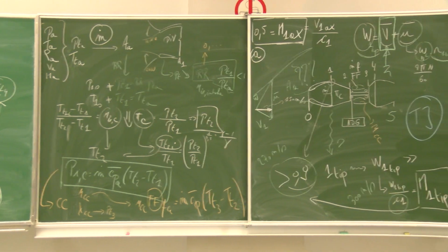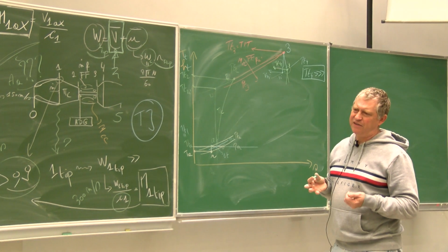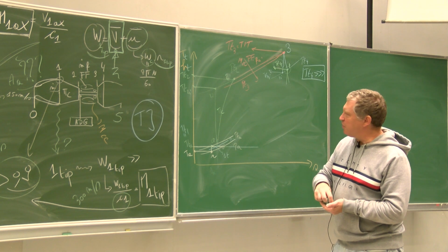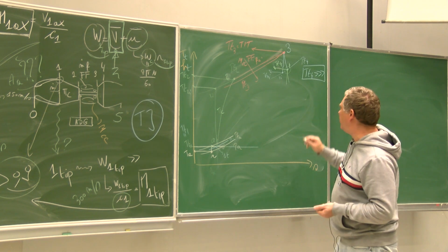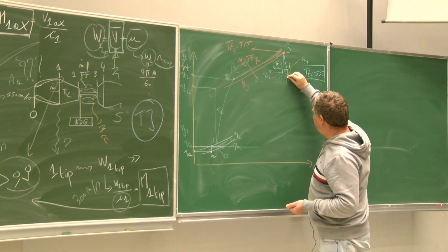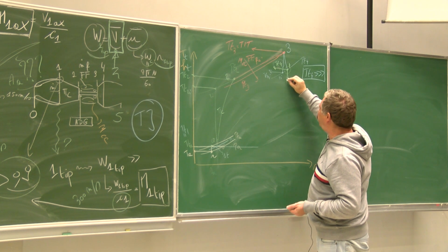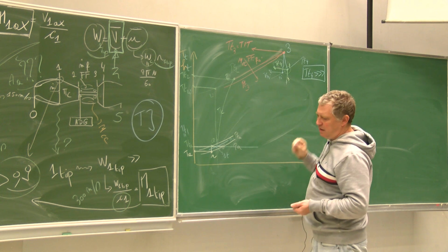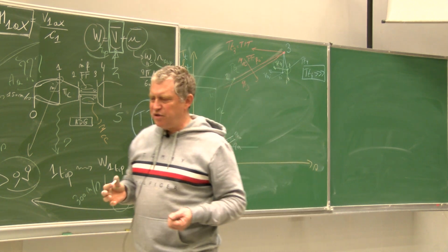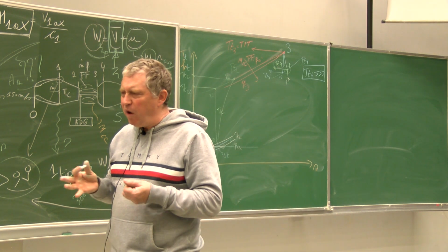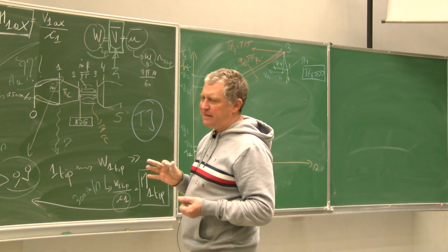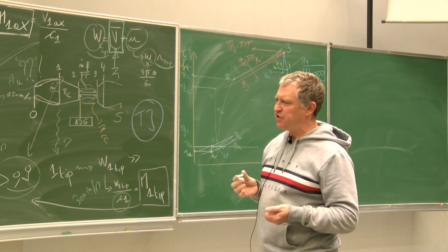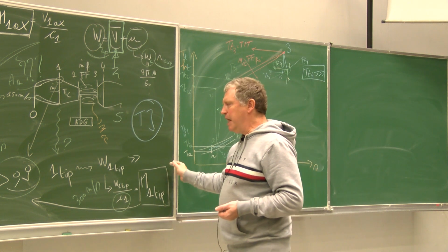It's not making a large difference. It would only complexify the situation, and I'm not introducing an isentropic efficiency of the nozzle, what I could do, but I will not do that. So I will follow this path, but in fact, I'm not making really the difference, and I will consider that the exhaust nozzle is isentropic. I'm not really insisting on this difference in the notes and in the computations that we will do.